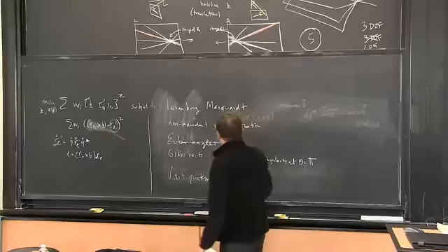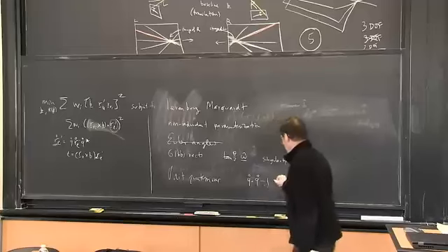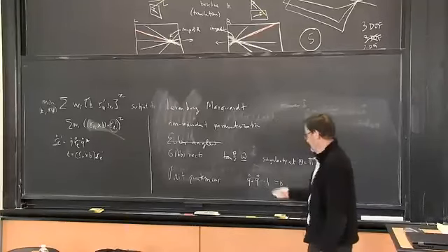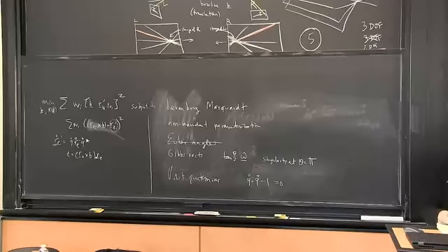But this package allows you to add additional constraints. So you just pretend that this is another equation. It will try and come close to satisfying that equation while satisfying the other equation. You may need to play with the weighting of different components, but that works very well. It converges pretty rapidly.